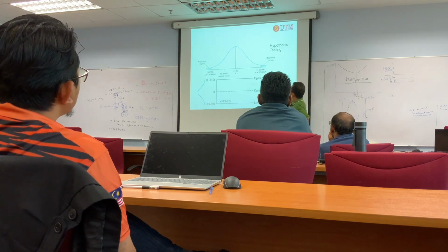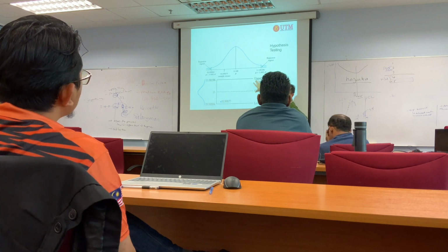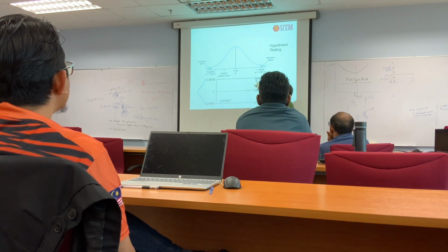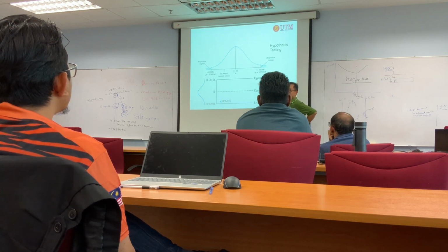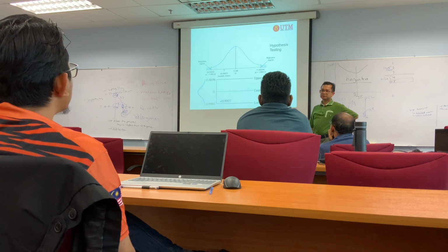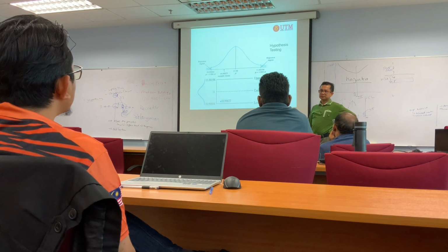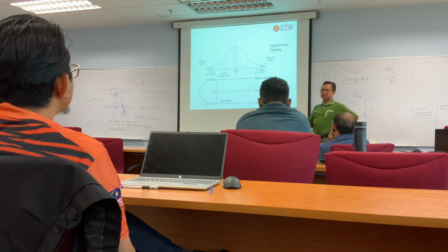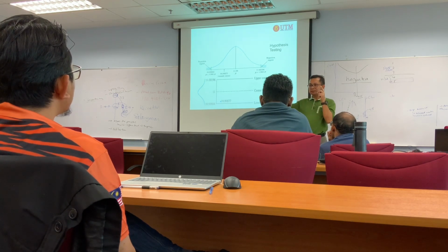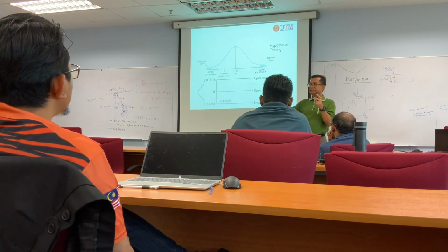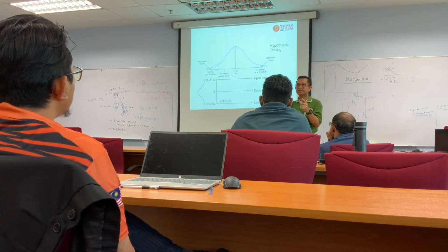How do we get 1.960? This is 3 sigma. How do we calculate 3 sigma from the data? From the data, we calculate the standard deviation. Sigma is standard deviation. Standard deviation multiplied by 3, that's the distance. But the standard deviation here is from simulation data, not actual data. Actual data is a company policy. For this process, what is our value for standard deviation? Because in the company, they should have their historical data.